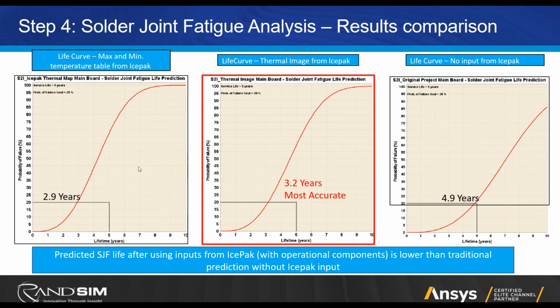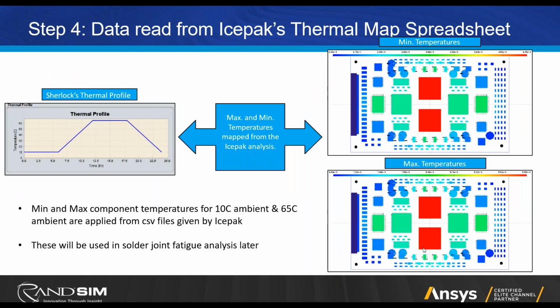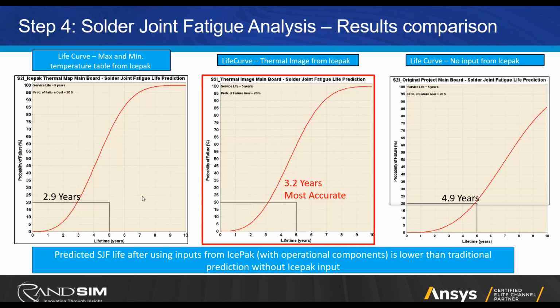For instance, if we had just used the maximum, things are going to fail a little bit earlier, and this is intuitive because instead of the gradient over those chips, with lower temperatures at certain parts of the chips, those parts which were a lower temperature are now a higher temperature. So of course, more temperature gradient, more thermal expansion, more failure. So you can use this to really dial in when your devices will fail and plan accordingly.